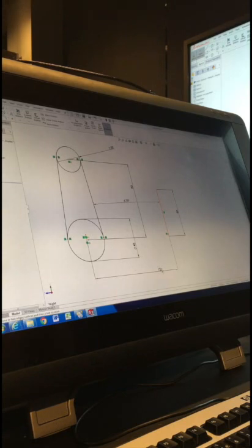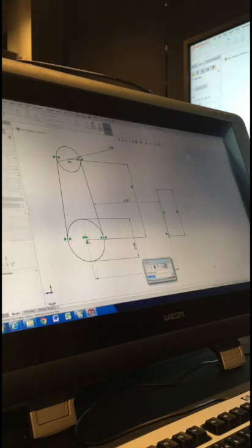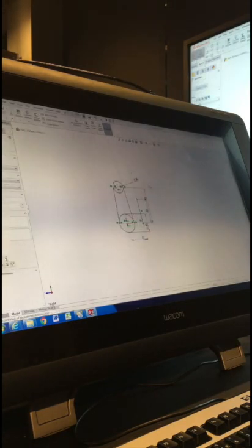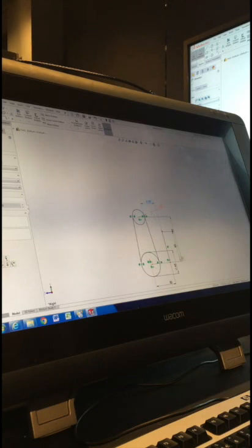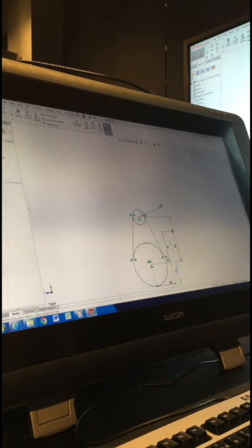All right, so if I change this number here, 120 to 50, see that angle, actually it hasn't changed at all. It's not going to change by that. What it might change by is this dimension. If I change this to 80, now that angle changes. All right, so that's a driven dimension.